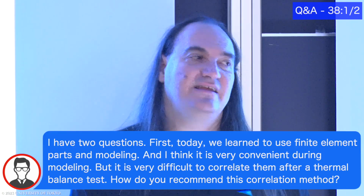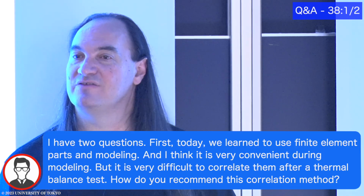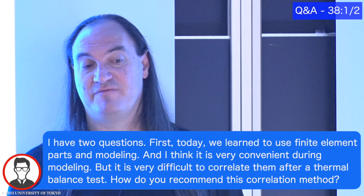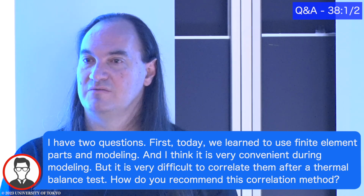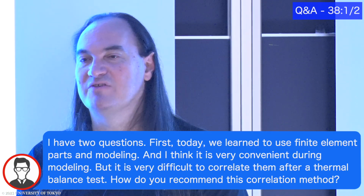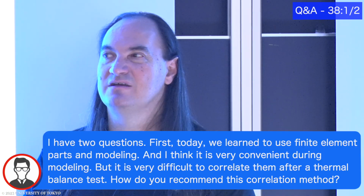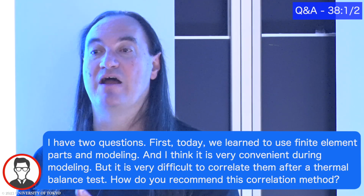I think that finite elements aren't going to be any more difficult to correlate than surfaces or finite difference. The uncertainties that you deal with in correlation are primarily at interfaces, where I've got a contact conductance, E star values, maybe some uncertainty in optical properties. But usually we're not changing geometry unless the geometry was never modeled in the first place.